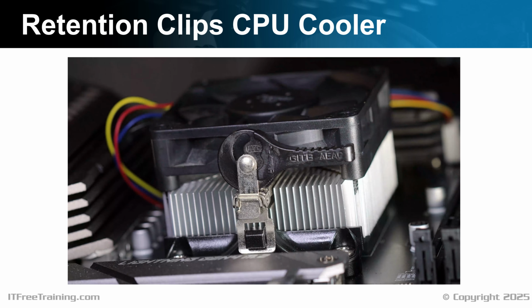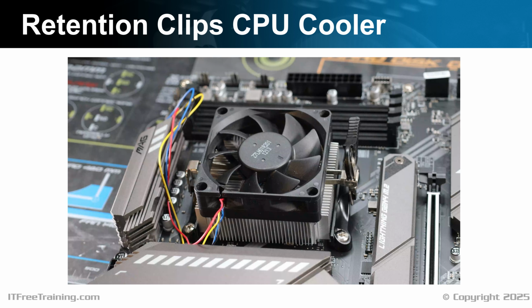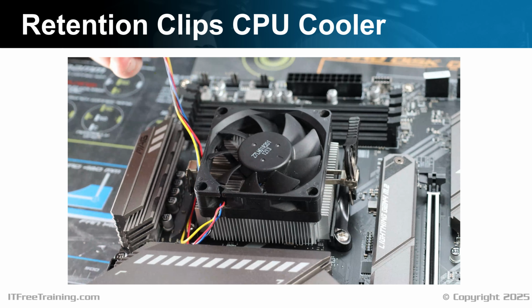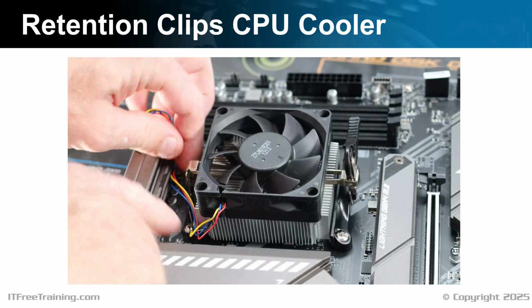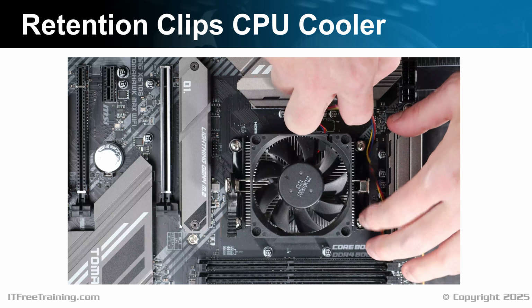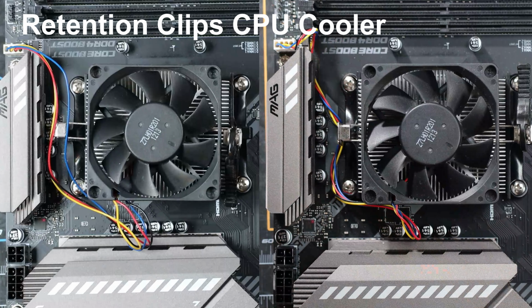The CPU cooler is now locked into place. These CPU coolers are not too hard to install. I will now tidy the fan cable up a bit. You'll notice the four wires will easily come apart, meaning they can get stuck in places they should not. So I'll unplug the cable, give it a few twists and then plug it back in. Once done, notice how much better the cabling is than before.